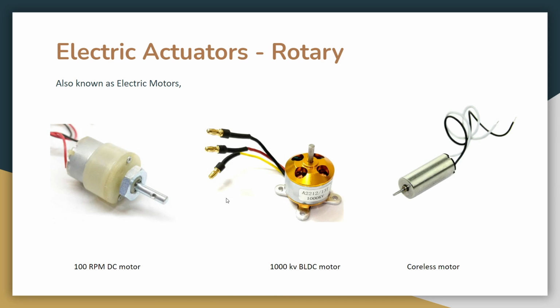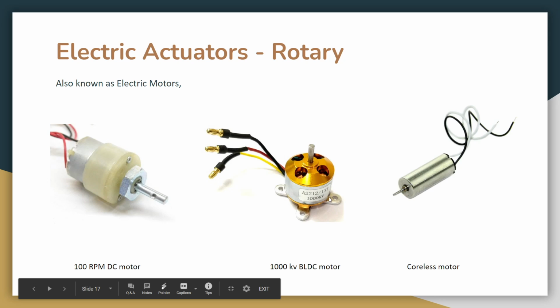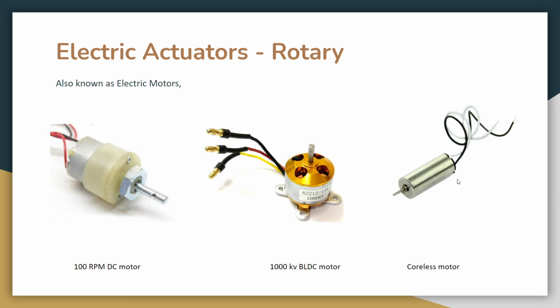Okay, I forgot to tell one more thing. That's a very small thing. So brushes: this is brushed, this is brushless, and this is also brushless. The main reason why these two motors do not have brushes is because, as you know, these two motors can usually be at very high RPMs. This obviously has a very high RPM, and 1000 kV plus is also pretty high RPM. They'll also be used for longer hours, because when you use these kinds of motors on drones, they usually fly for a good 15 to 20 minutes, depending on the application of its use.